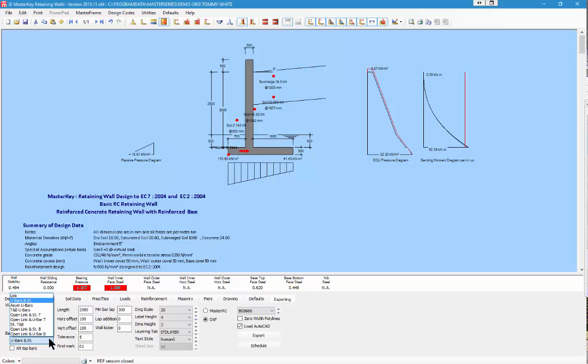We also have, for those shorter arrangements, and it will tell you if it gets too long, top and bottom U-bars, so they're pointing up and pointing down, or open links with a closer, and we will just accept the standard U-bars and straights. So we set a length that's into the page of wall, and we can do anything up to our 12 meters.